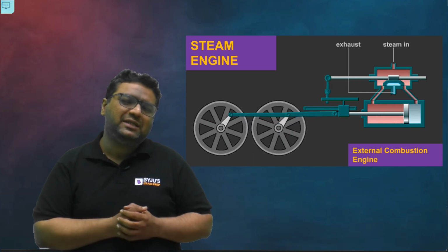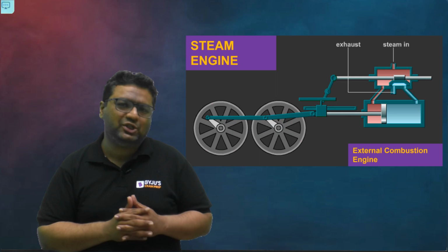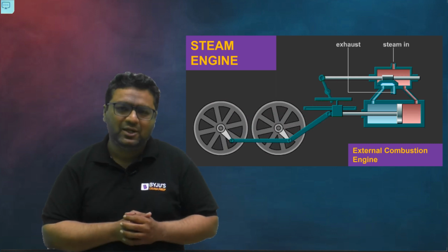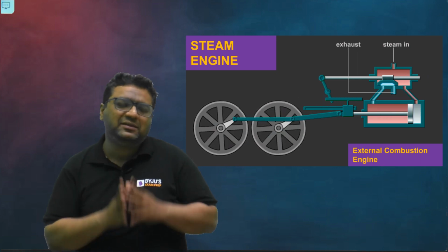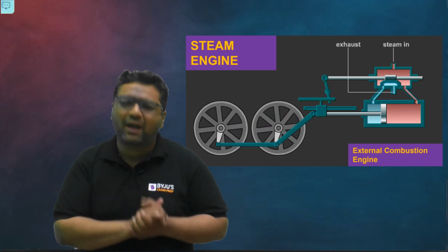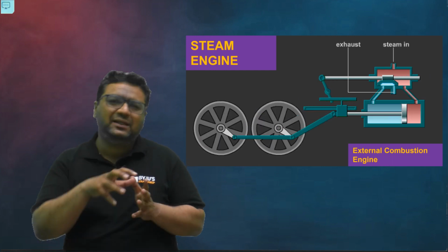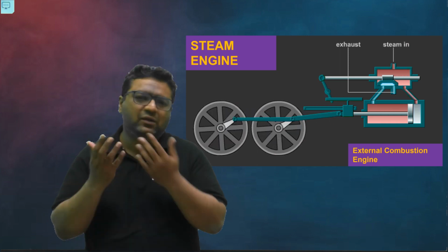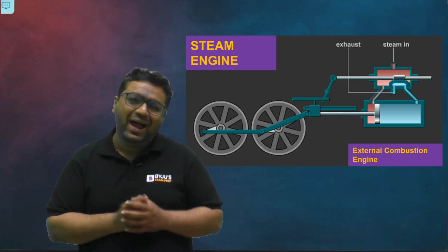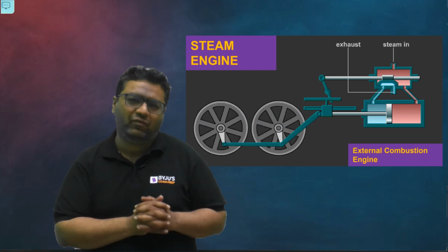Now you may be thinking, sir, how can the steam do that? Actually, my dear, the concept of work is the movement of the piston, which we study in general in thermodynamics. So here, what is going to happen? We will be having some valves for intake and outlet. If you are talking about this cylinder, obviously somewhere around in the boiler, heat or steam will be produced, and that steam will be coming inside the cylinder from one inlet valve, on one side.